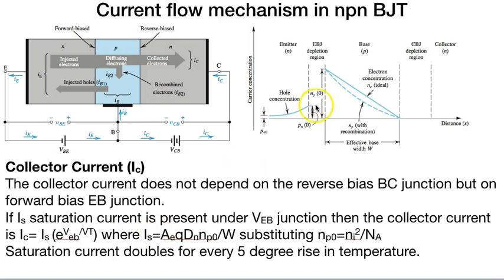As we have looked into charge carrier concentration, we found that the electrons decrease almost linearly in the effective base width, and these combine with the electron hole pairs in the process. Hence they have a linear decrease as they travel across the base width region.